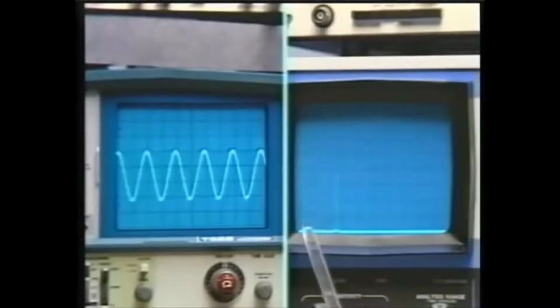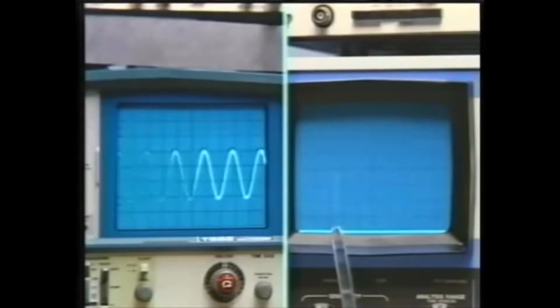We have, of course, the time domain display of the sine wave, and the spectrum analyzer gives us a frequency domain analysis and display, and the vertical axis is the amplitude, the horizontal axis is frequency, and as it's set currently, the frequency axis goes from DC, 0, up to 2 kilohertz, and that, of course, can be varied on the spectrum analyzer. And since we have a sine wave input, we get, as we would expect, a line spectrum corresponding to the frequency of the sine wave.